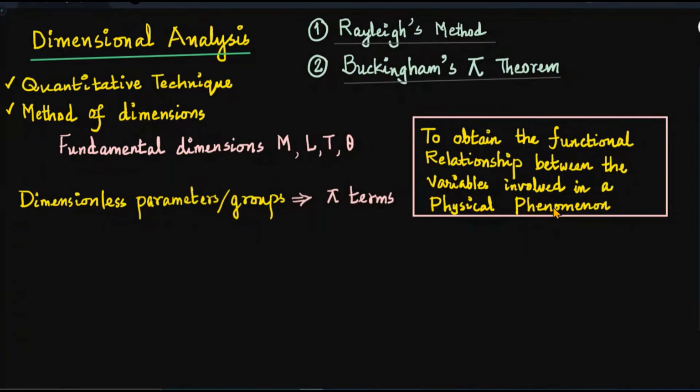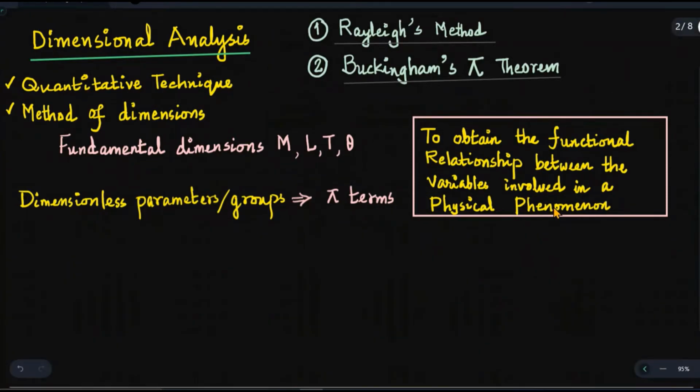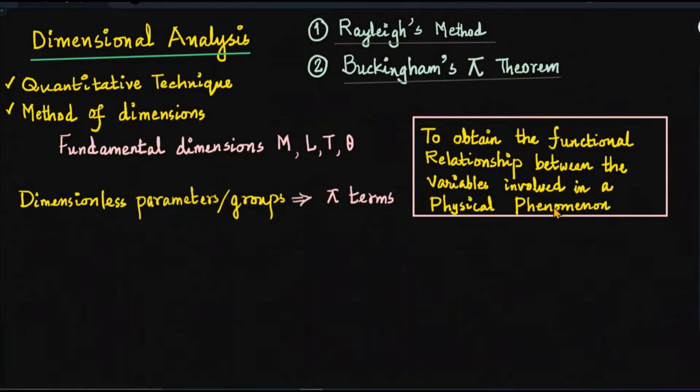Quantitatively, we express it as roughness of the surface of the pipe, which may be denoted by epsilon or the letter K. So pipe roughness K, pipe length L, pipe diameter D, and the other fluid properties like viscosity mu, fluid density rho, and average flow velocity V.